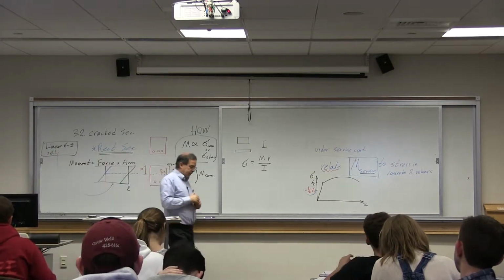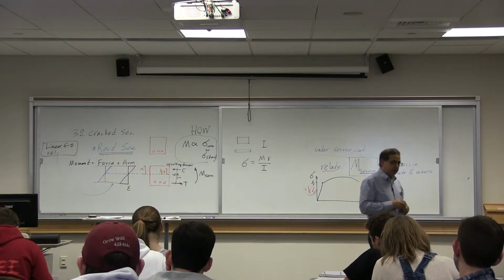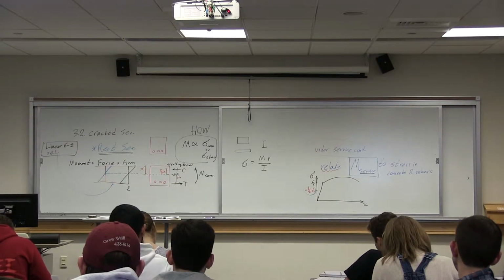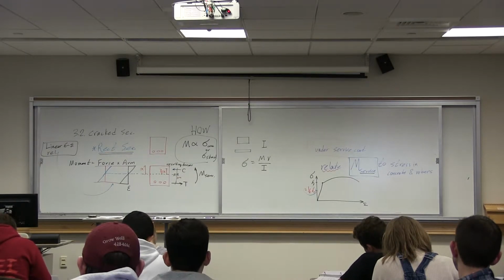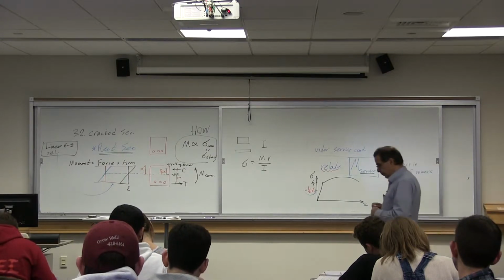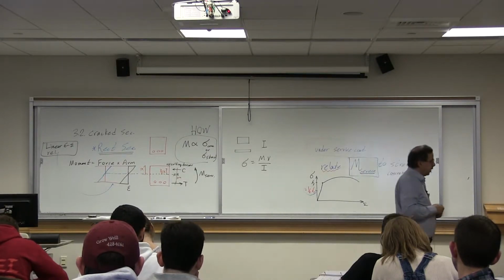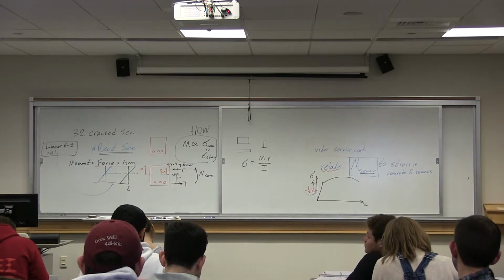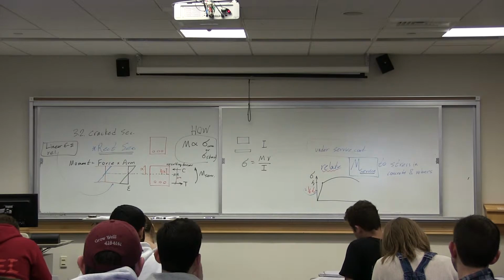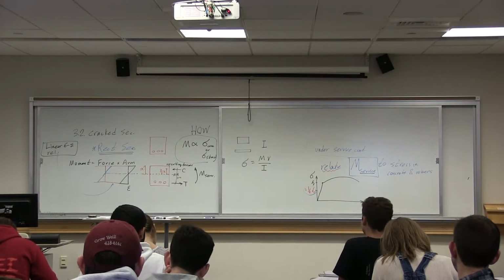Now, you said the resulting force will be at 2/3 from the base. What are you thinking about? The centroid of the stress distribution. Why should we look at the centroid of that stress? Because it's equivalent to the distributed load on the compressive part of the concrete. Is that a line, the stress applied to the area that we are considering, the cross section? Is the cross section in the compressive zone a line? What do you mean by line?